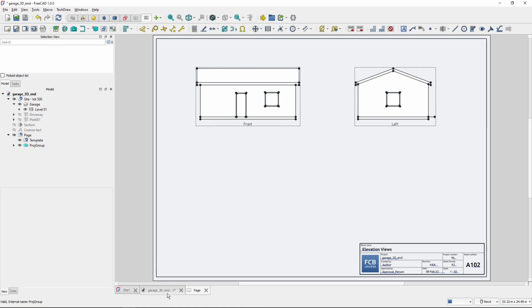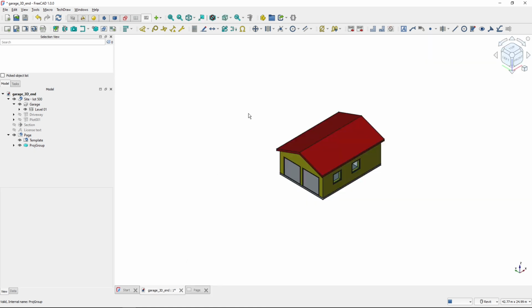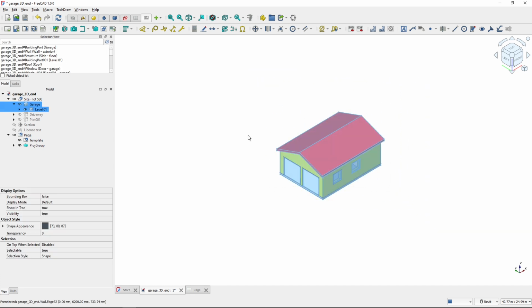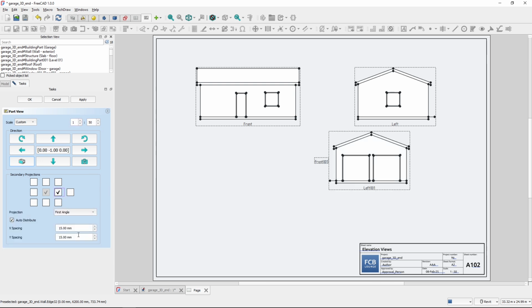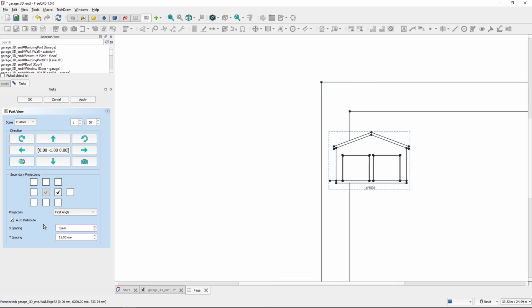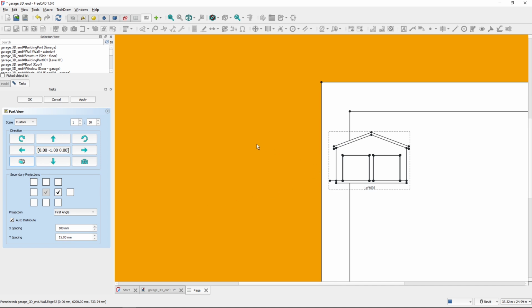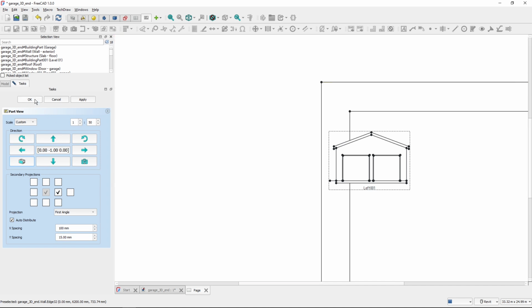So now I will go back to my 3D view and create again box select, Shift B, drag around these objects, create insert view, place it here, and I will change the scale to 1:50, and I will use, I knew that I will use again this one, and X spacing will be 100. And now I moved too fast, I think.